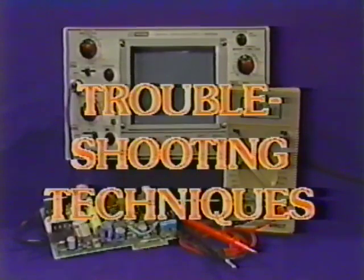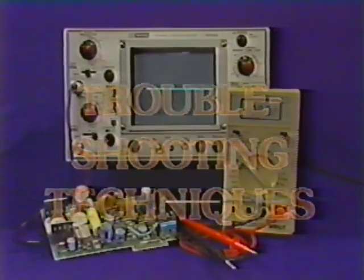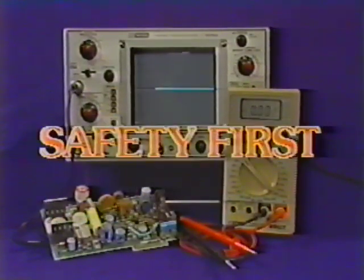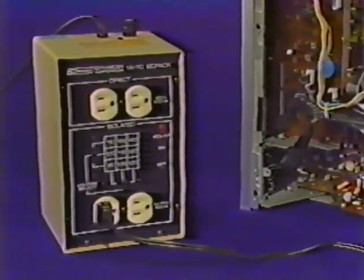The techniques used in troubleshooting a linear power supply are relatively straightforward. The multimeter and oscilloscope are the only test instruments needed to identify most problems. All safety procedures should be followed when troubleshooting a power supply. Remember that it is line-powered and potentially lethal. When servicing a transformerless supply, always use an isolation transformer.